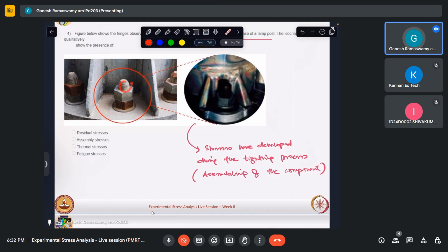And perhaps in the good for construction drawings or the assembly schedule, we will mention that this is the level of load or torque that needs to be applied to the bolts, no more, no less, which can be checked. So that is how we have to address this.